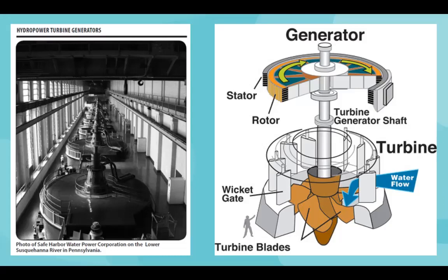But essentially it's a large generator, and you're using electromagnets to circulate electrical current through the loops of wire around the stacks of magnetic steel laminations. They're called field poles and are mounted on the perimeter of the rotor. The rotor is attached to the turbine shaft and rotates when the turbine rotates as the water goes through. So this moves the electromagnet, and in this case causes electricity to flow and voltage to be developed as it goes through.